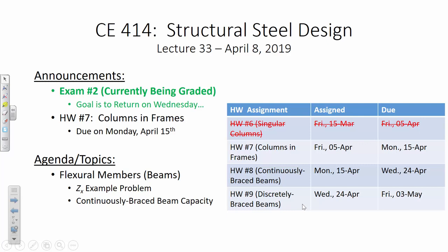Today, we're going to go back to that concept of a plastic moment and go back to this section property of ZX. We're going through an example where I compute ZX. I'm also going to compute, on the side, what is SX, the section modulus? Everybody in here should know how to do that. I showed you how to do a lot of this in mechanics of materials or reinforced concrete design.